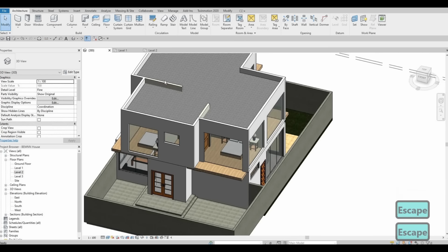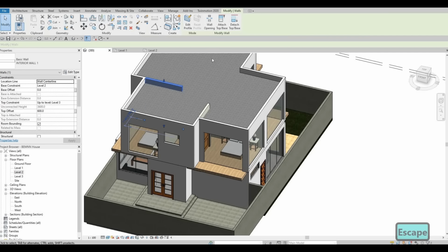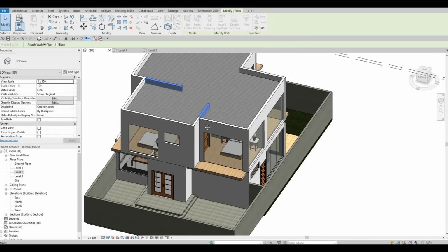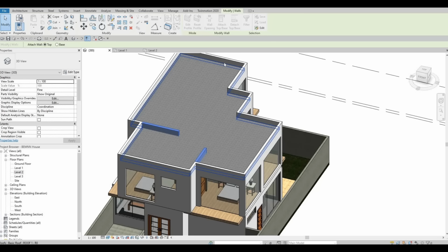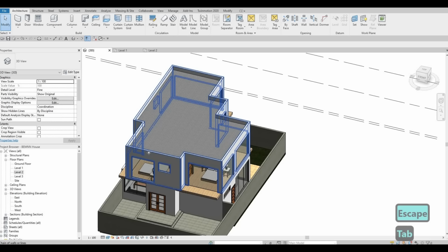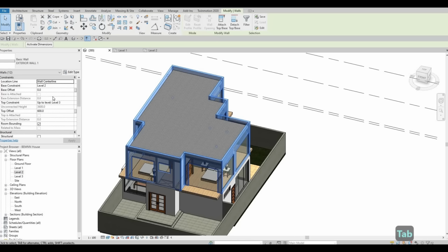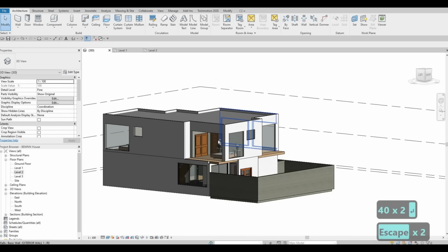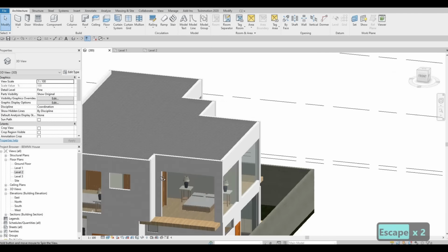Now when we go to here, we could basically pull this down. So select here and select there, click Attach Top/Base, and then select the roof. It will disappear. And then now you can select all the exterior walls again, and you can manipulate from 400 if it's too high, to your liking. So it will look like that.